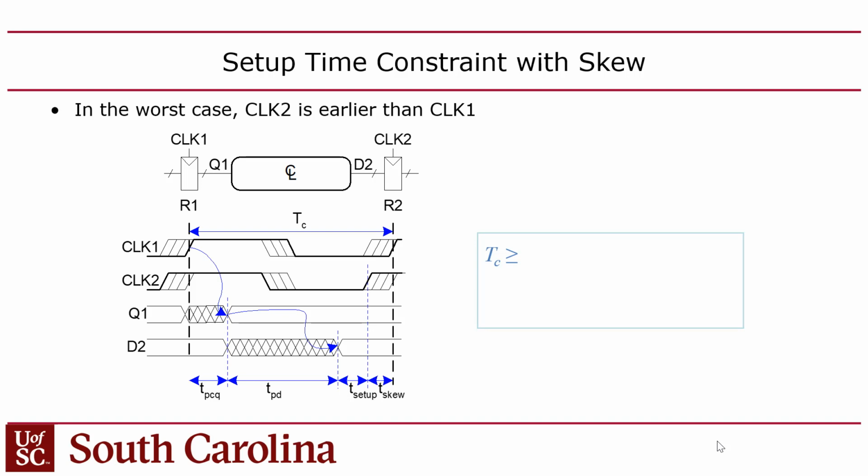What that's going to do is add effectively more delay from R2's perspective. When you calculate your propagation delay, the input to this logic is going to be running behind. The propagation delay is how long it takes the register and the logic to propagate, but if they both got a late start, that's going to cut into the clock cycle even more. So R2 is going to see its input coming in even later than it would be just because of the propagation delay.